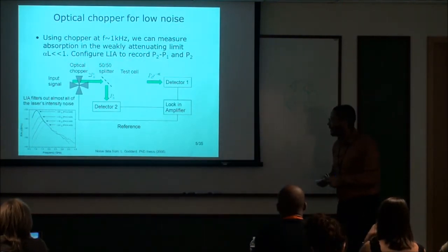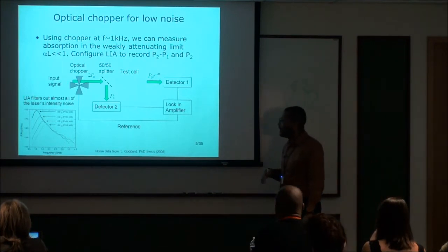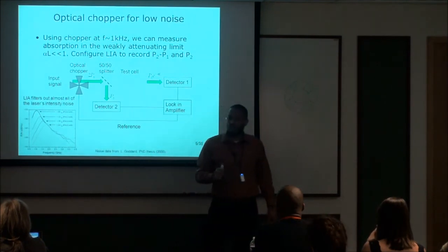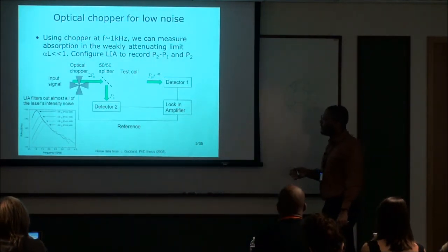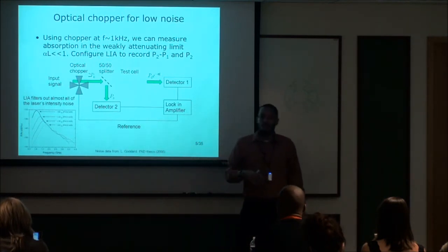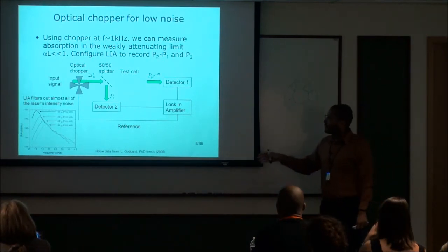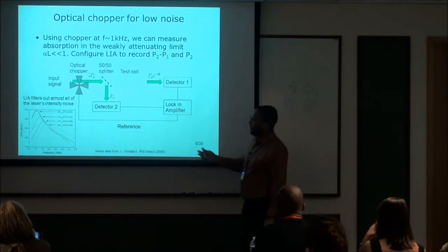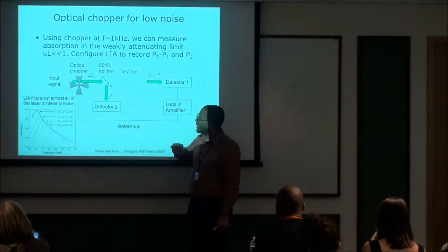The light output is not exactly 3 milliwatts. It fluctuates in time. Shown here is the intensity noise spectra. If you look at it carefully, at high frequencies there's a peak in the noise of a laser source. If you were to continue to measure this down to lower frequencies, you'd also see that there's a noise spectra for lower frequencies, and that there are things like 1/f noise. So 1/f noise, also known as flicker noise, can affect the powers that you see on your two detectors.